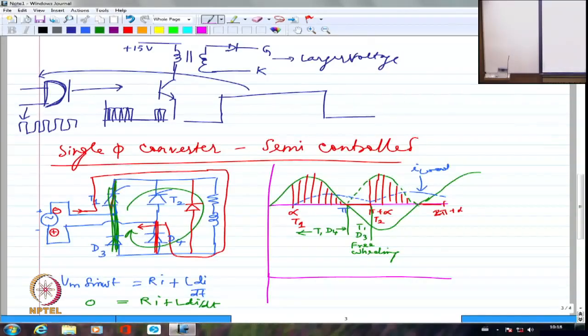So fortunately, in a semi-controlled converter, when we operate it in actual practice, we hardly see the supply getting short circuited. You got his question? He was asking basically that if this is in reverse recovery and this has already jumped into conduction, you are going to short circuit the supply. If you are going to short circuit the supply, then it's not really good for the supply, normally.